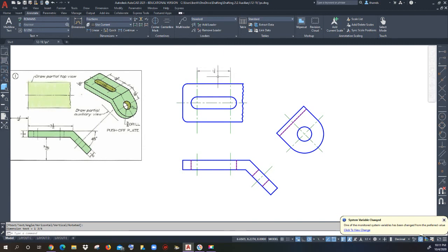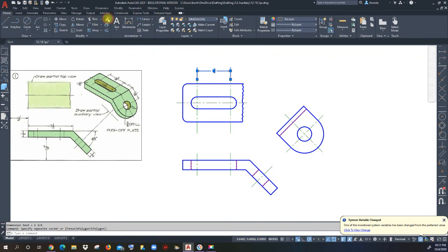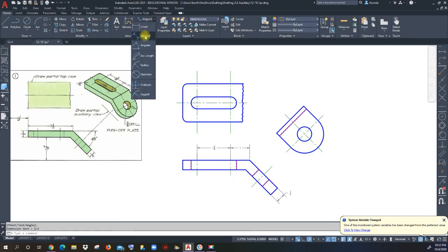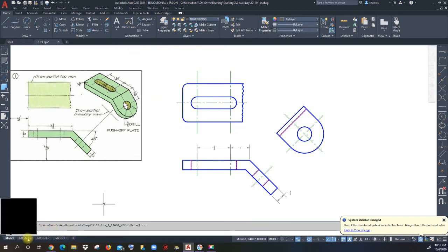Instead of putting this up here on the top like it would be on the top view, I am going to place it down here at the bottom because I'm going to need this 1-inch reference line, because that's where that distance comes from. So think about where dimensions are referencing from, where they start, and dimension your part, and then you're ready to place it into your layout C.